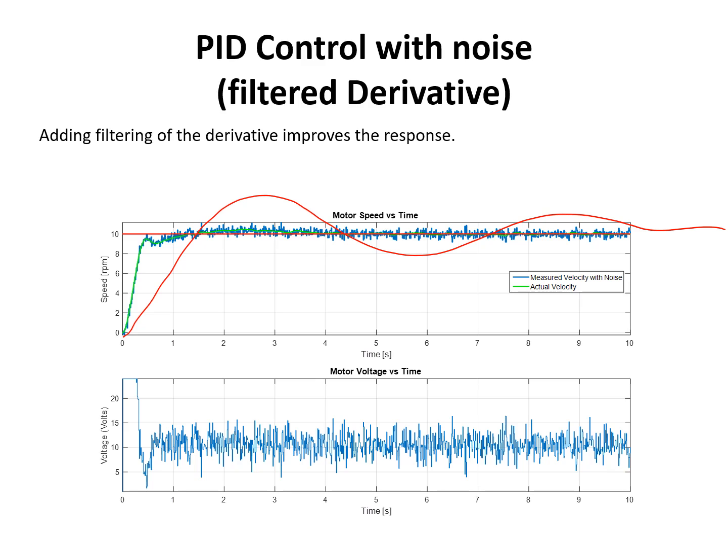So in practice, when you have to add a derivative term, be careful. Note that simply by differentiating, you might add additional noise to the output of a system. So be careful when you start adding it. At least plot the derivative error to see whether there's quite a lot of noise on it before simply using it.